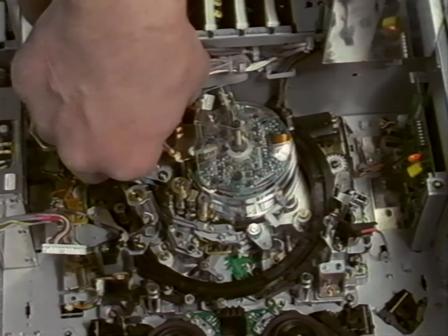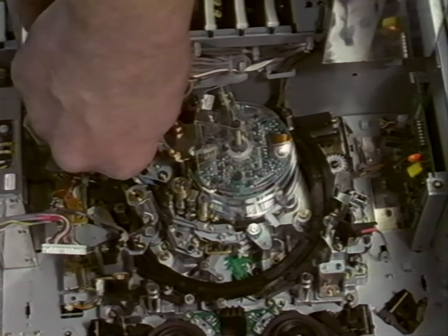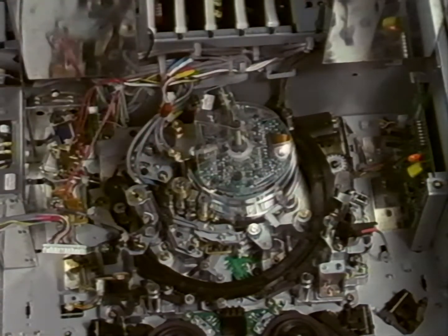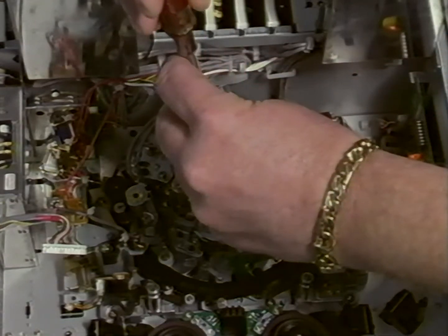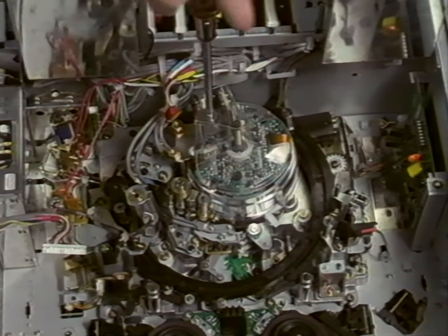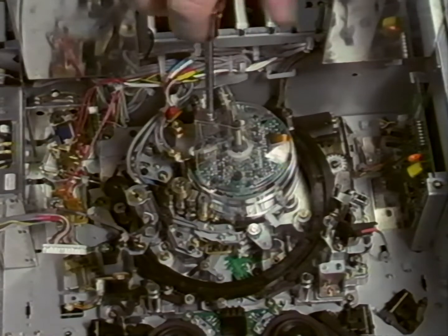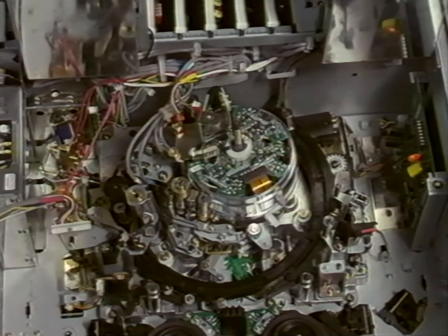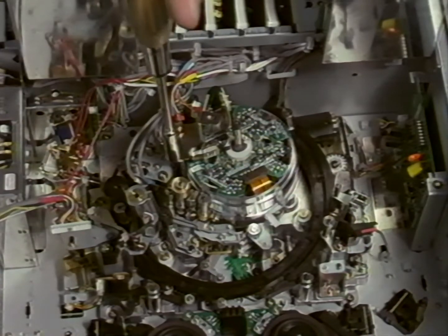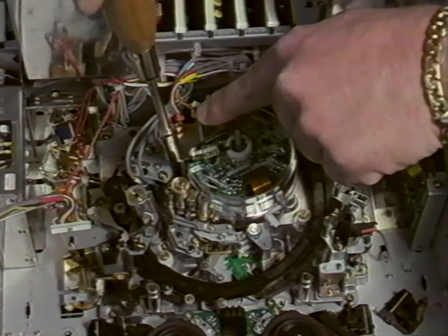We begin by removing the brush assembly. The cleaning roller block, as you can see, has already been removed. Two connectors are disconnected from the SR26 board. These are CN661 and CN662. Now remove the plastic brush cover protector. The brush assembly is removed by using a 7mm socket driver.